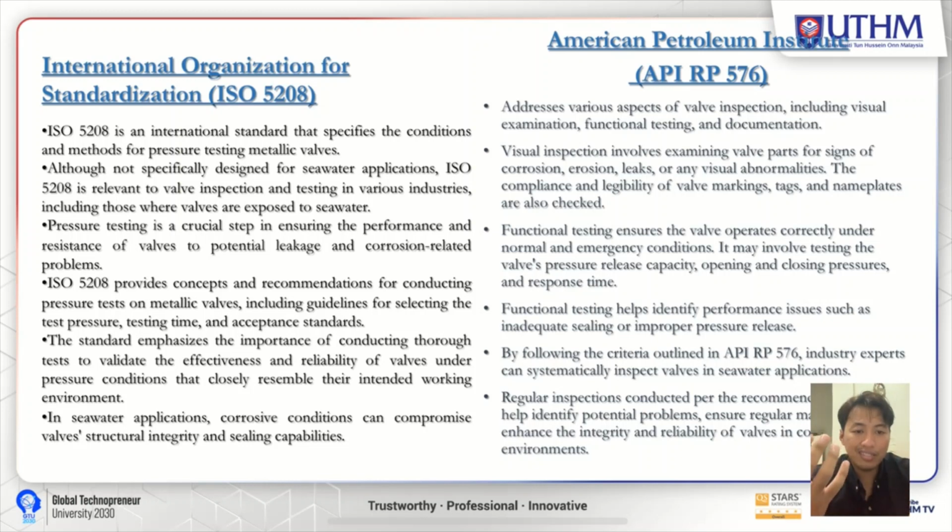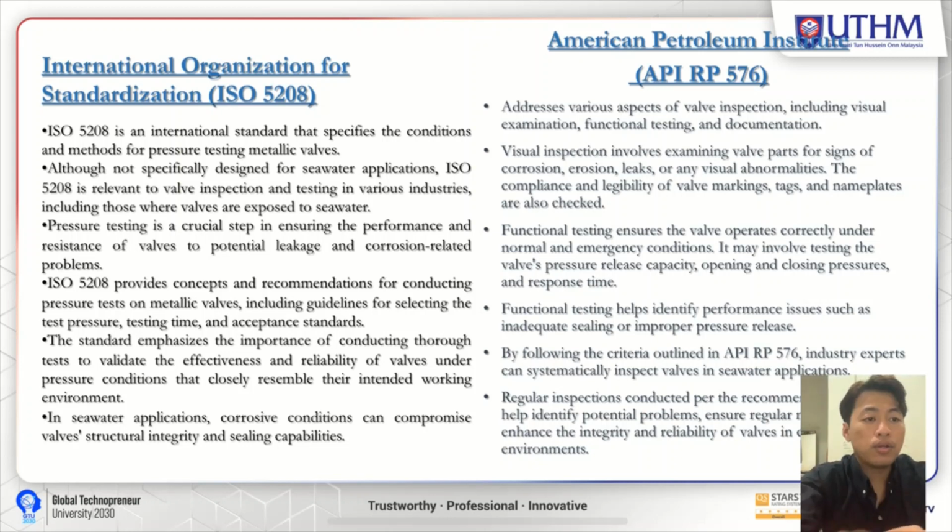For seawater applications of the valve, the corrosive conditions can compromise the valve's structural integrity and sealing capabilities. Functional testing helps to identify performance issues such as inadequate sealing and improper pressure release by following the criteria outlined in API.